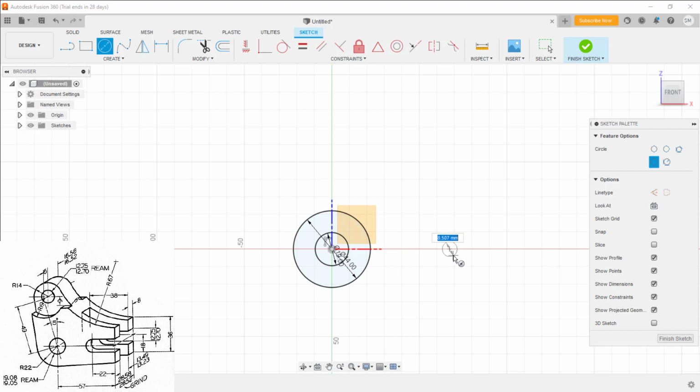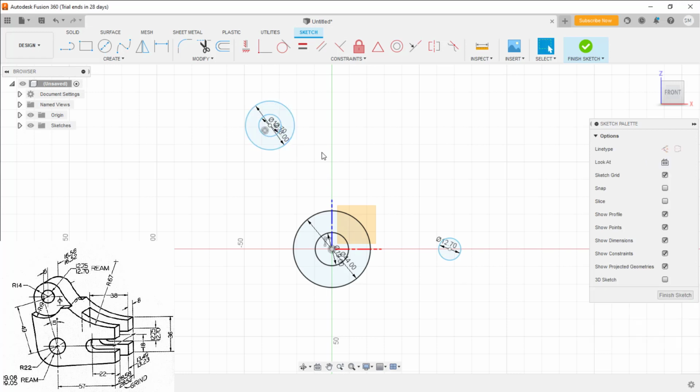Remember, if you enter the value and hit enter, the tool will get deactivated. You just keep it like this only, it will be locked, and you just need to click and go ahead with the next. This is what you need to remember if you want to continue the same tool again and again. So here let's do the same thing. I need a circle of 28, just lock it, just use 12.2. Yep, done. Click plus left click.